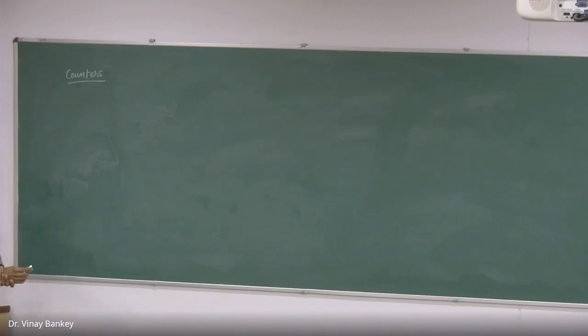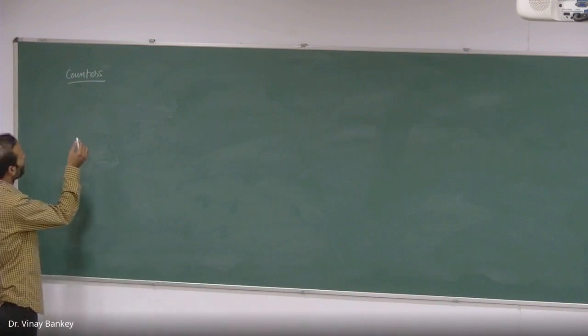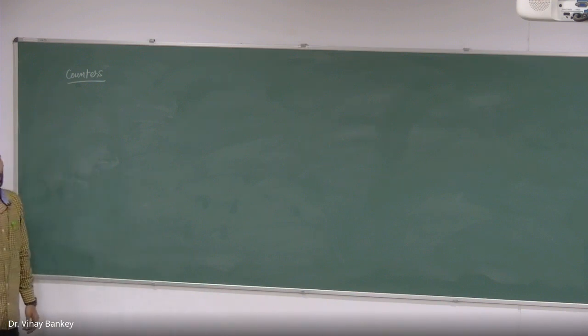All right. So in the previous lecture, we were discussing the counters. And we saw one example. We took two flip-flops and arranged them in a specific manner, and we tried to obtain the timing diagram based on the clock pulse. And I specified that the counters are classified, based on the clock pulse, into two types. First is the asynchronous counter, that is also called a ripple counter, and the second is the synchronous counter.